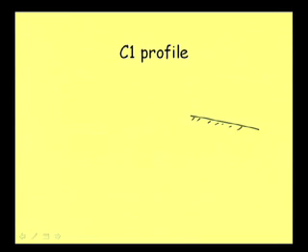Okay. Now, if it is critical slope, then this NDL and CDL are the same line, and that is why the zone 2 is not existing here. Rather, we have zone 1 and zone 3, and any profile forming in the zone 1 we call C1 if it is on critical slope.